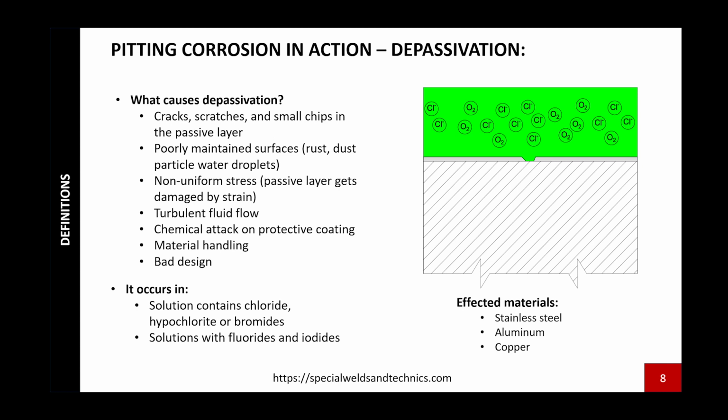Austenitic stainless steel, it's a typical one. That's actually the reason why we need duplex materials. Seawater application: aluminium, copper. So for seawater application we need special copper alloys, let's say Admiral brass or something, to be able to use in seawater application.